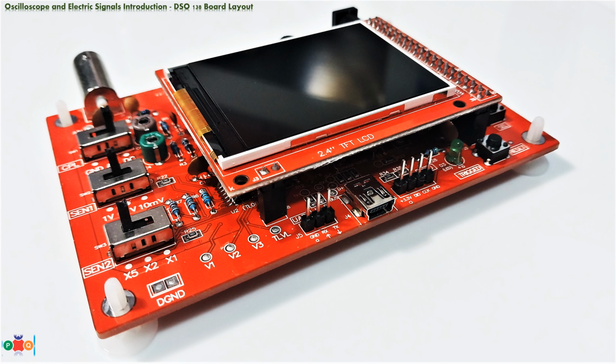Here, you can counter and say, well, why not generate a strong signal in the first place and be done with it? Well, simple answer, it takes a lot of power, and power is expensive. So, the guiding principle in electronics, like in any business for that matter, is to produce the most result with minimum cost, in this case, cost being electrical power. If we take a microphone and record sound, the resulting electric signal is very weak, measuring in millivolts, and that is pretty weak.